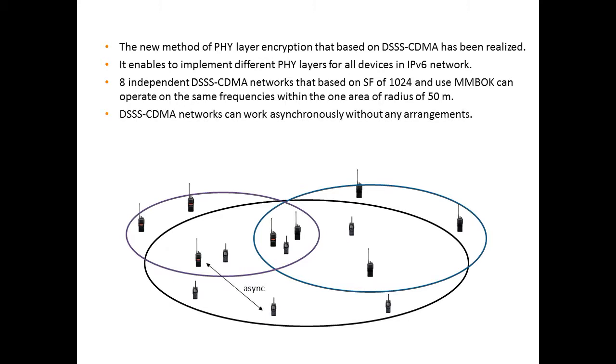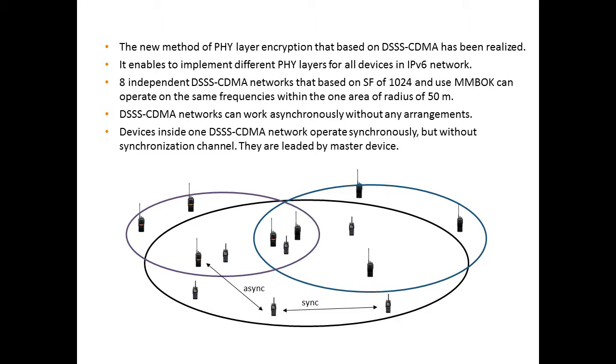Independent DSSS CDMA networks can work asynchronously without any arrangements. Devices inside one DSSS CDMA network operate synchronously but without a synchronization channel. They are led by the master device. This is all for today.